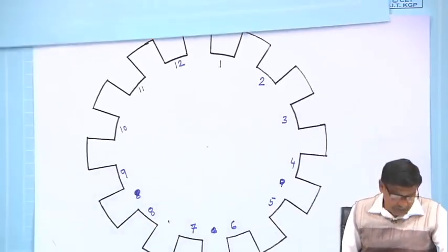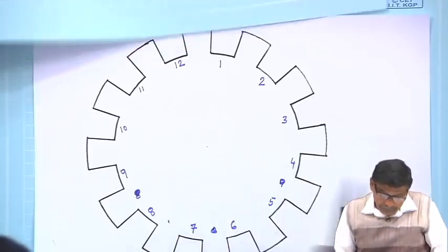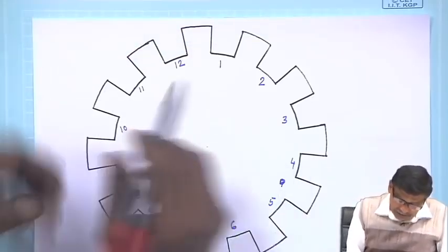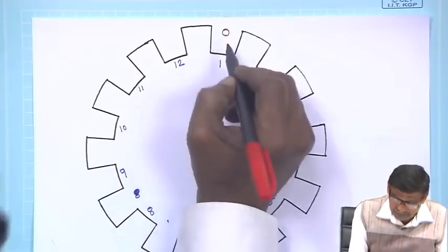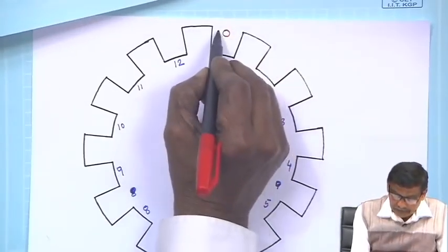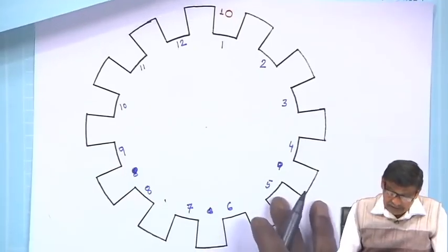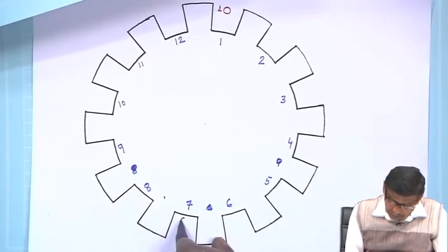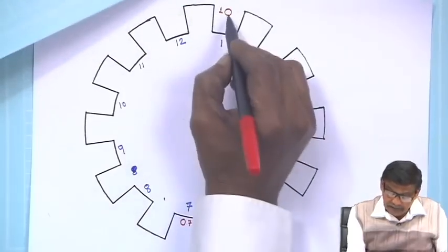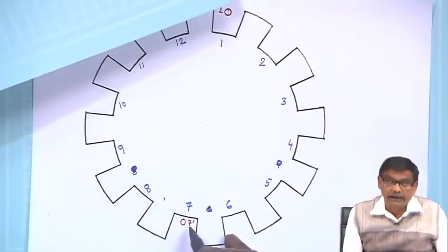So, the R phase coil winding I have shown you like this, but the actual disposition of the coils will be like this. You take the first coil and let me use the red wire to indicate R phase. So, it is 1 on the top, this is 1, and its return is at 7, diametrically opposite, because it is a 2-pole machine, it is 7 dashed. This is 1, and this is 7 dashed.